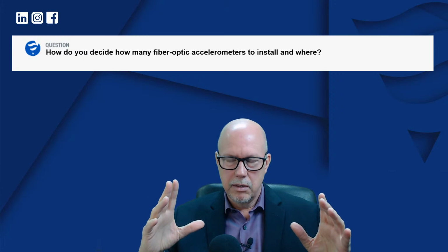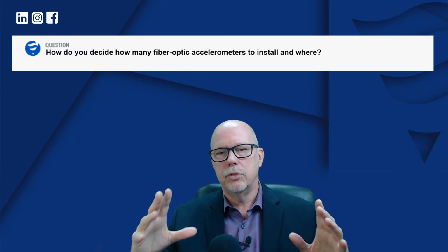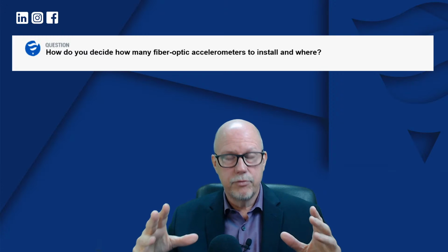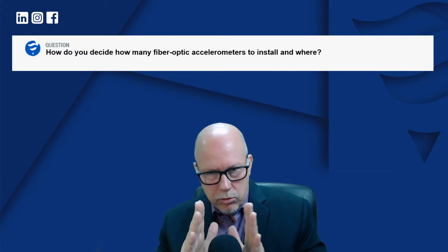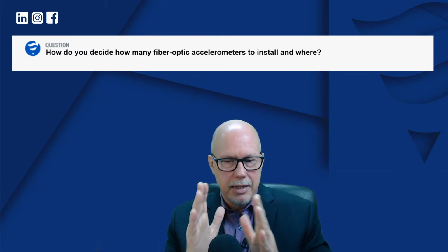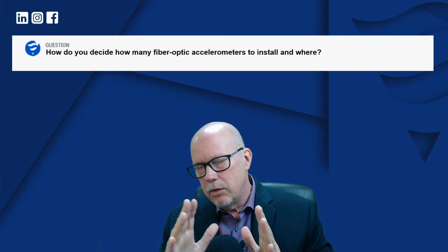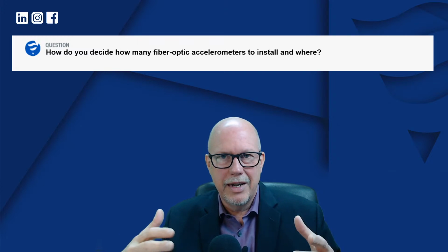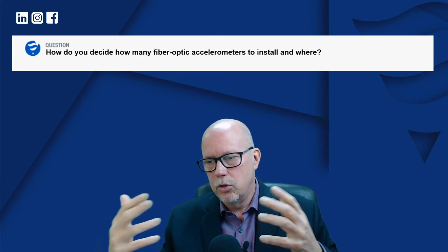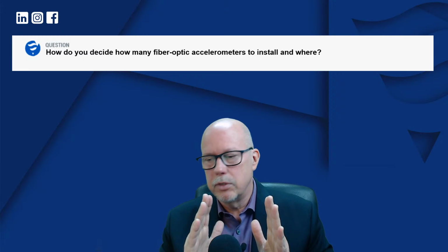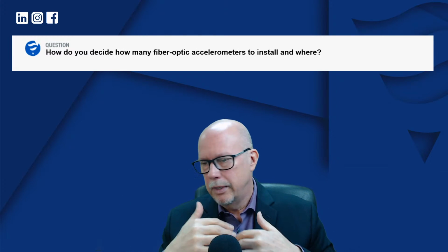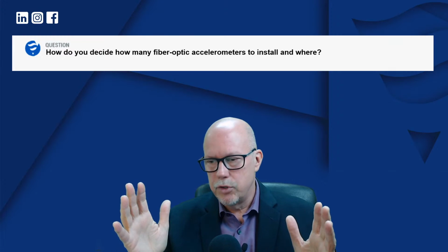It's a known procedure to determine where the natural or resonant frequency is. And there are standards for that where you have an exclusion zone. You should never have a result in that zone. And if you do that, at least you know that you've done everything you can to try to avoid having your windings anywhere near the electromagnetic frequency. So bump tests should be performed at all major outages for sure.